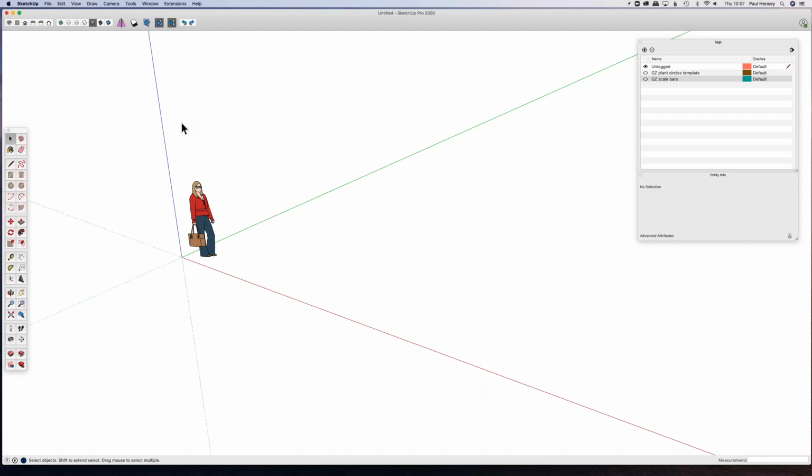I'm using SketchUp Pro 2020. I've not got any particular setup. I've got no enhanced graphic card. I'm just using 32 gigabytes of RAM. When you're using or creating terrain, it can create a lot of polygons, especially with larger areas of landscape. And that gets even more onerous when you're starting to use plants.